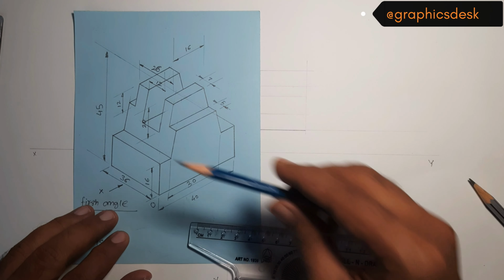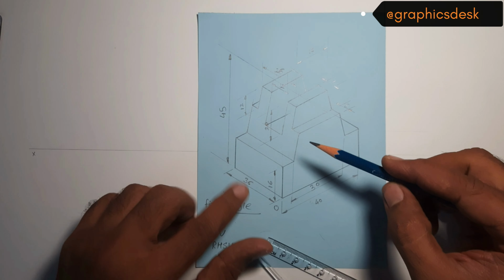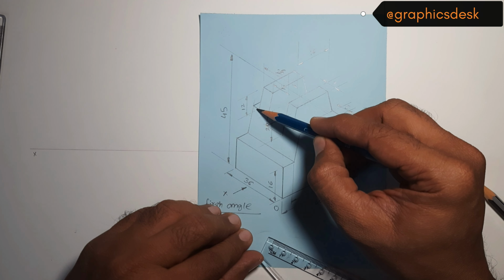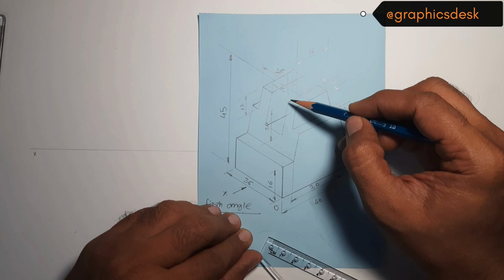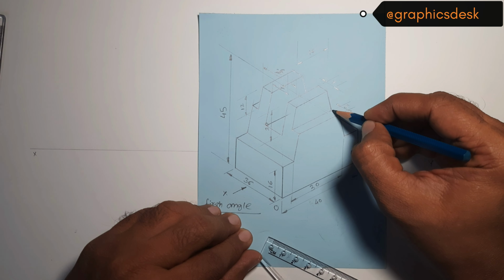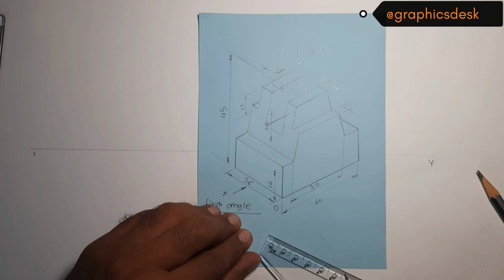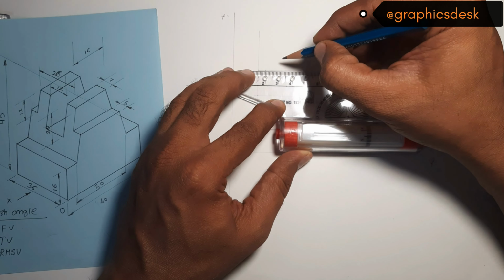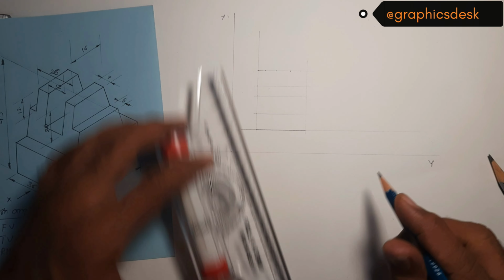Okay, so now I have only marked these levels as these three lines, but to do the construction, we'll have to measure the horizontal distances elsewhere. That means distances in the z-axis. So let's measure that. What we have here is, this is 5 mm from this face, again 5 mm from this face as well. Then we have this as 7 mm and the gap between is 12 mm. Now we already calculated 36 on the basis of the same. So we'll measure 5 mm from this side and 7 mm from this side. So let's measure that from both the sides. Alright, so let's mark the vertical lines from these points.